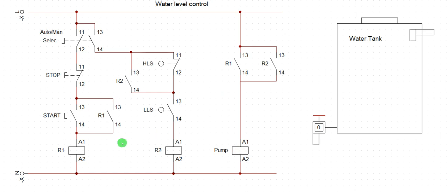Now one of these contacts is here. When this one closes, this one will close as well. That is, both of them will change state simultaneously, close, and activate the pump. Now, if I want to operate the tank by auto, I will activate this to open this and close this, and I will have power here. So when I have power here, then each of these two flow switches, this is my high level switch and this is my low level switch.